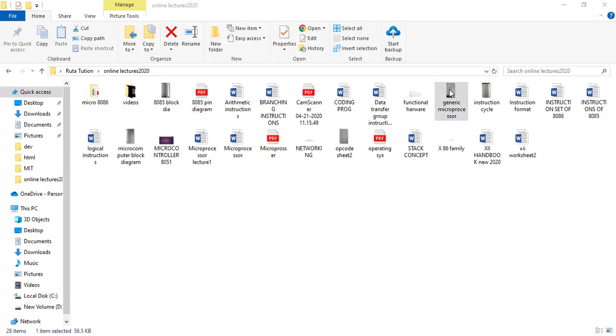So if you know the 8085 block diagram, you have a similar diagram. See, IR, instruction register, instruction decoder, and timing and control. So this part is same as 8085. Then in the register block, you have HL and program counter and stack pointer. Now the interrupt block is given to the timing and control section only here. So interrupt control where only INTR is the interrupt.